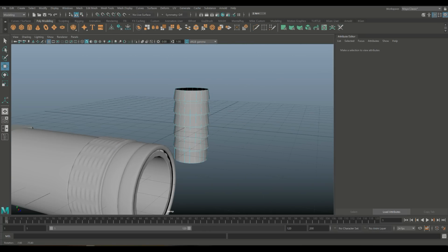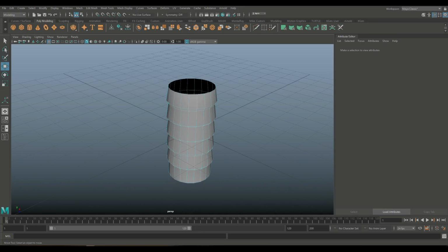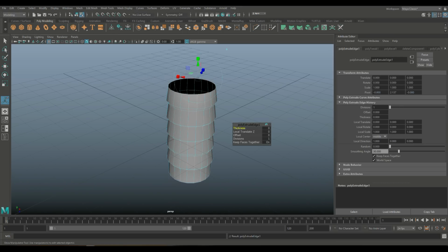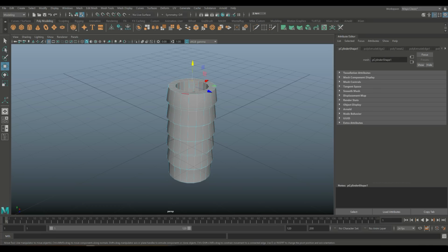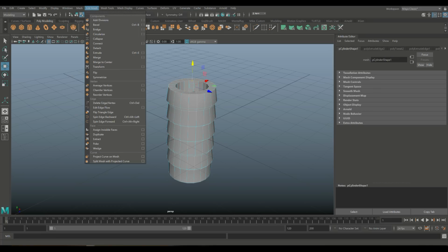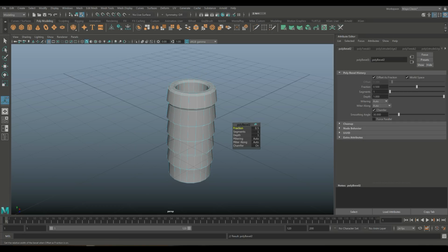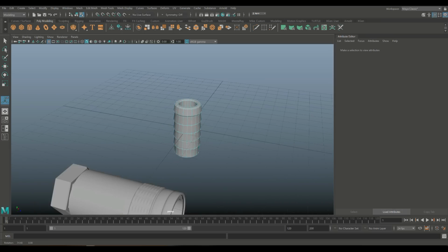Okay, so that's a good shape. And let's see on the inside here, we're gonna double click on this, Control E, R to pull in like this, G to repeat, W to push down like this, and then we're gonna go in here to select these guys, go to edit mesh and bevel, which is a good end.